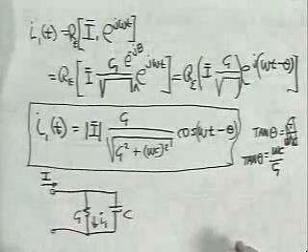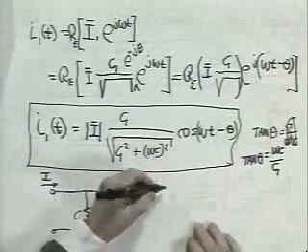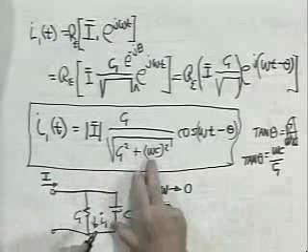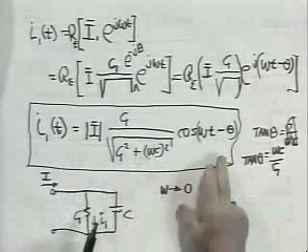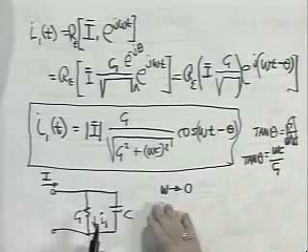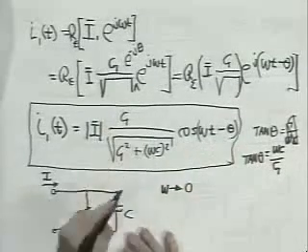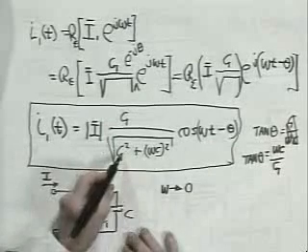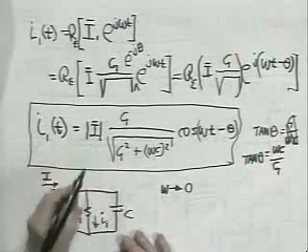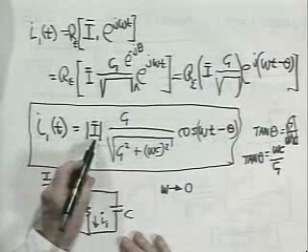So if I look at the circuit and say, does that make sense? Let's think about it. As the frequency goes very low, as omega goes to 0, this number gets smaller and smaller, and this angle gets smaller and smaller. Its tangent gets smaller and smaller. So in the limit, as omega goes to 0, this argument is just omega t. This relationship is unity, because as this gets small compared with g squared, I can ignore this, take the square root, it's g over g, and all I have is that the current in the conductance is equal to the current that I applied, I.